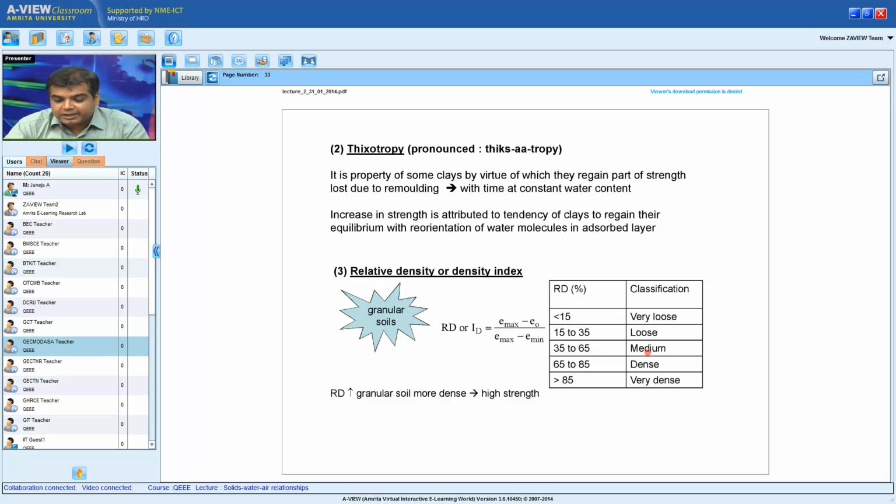It gives a feel. You remember the stress strain hump which I spoke about earlier in the lecture today. The size of the hump is controlled by this relative density. If it is loose, there won't be any hump. If it is very dense, the hump will be high. Of course, we spoke about the hump in terms of angularity. Angularity also plays a role.